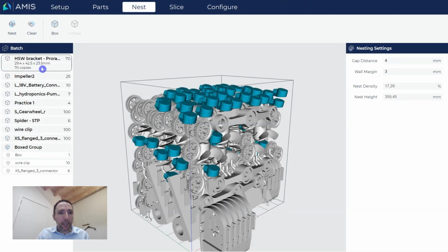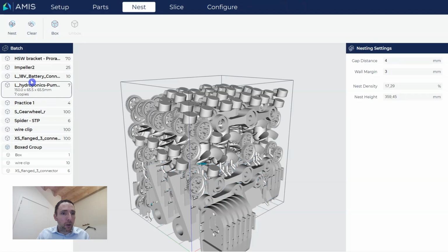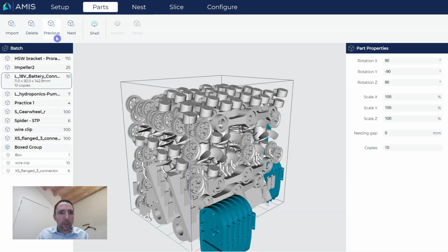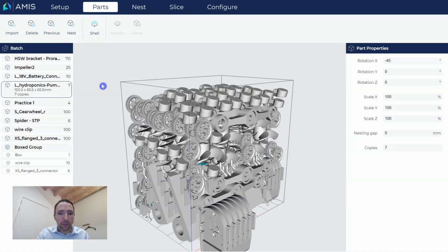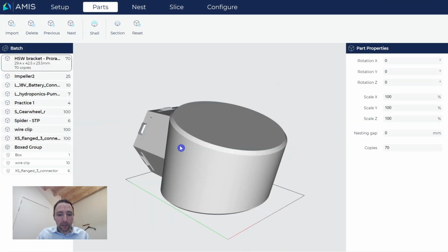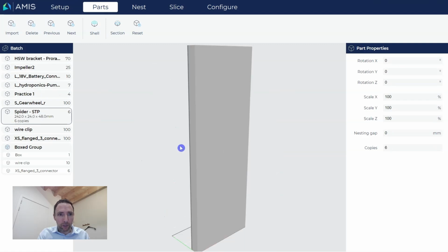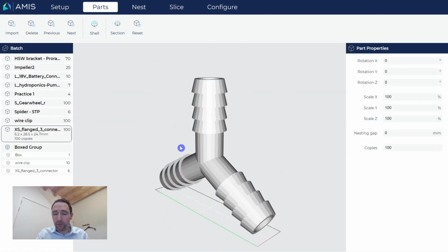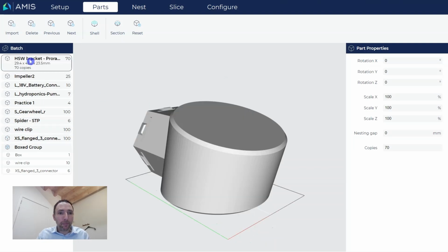So that was the first part I wanted to work on. That was this one. I go back into the part view, and there you have previous and next. Also there you will see that you have a shortcut, Alt P for previous and Alt N for next, which you can then use to actually go through your parts, as you can see here. That just as well works when you're inside the part. You can just go Alt N to go to the next part, to quickly go through all your parts to see if all the settings are okay, or if you perhaps want to change something.